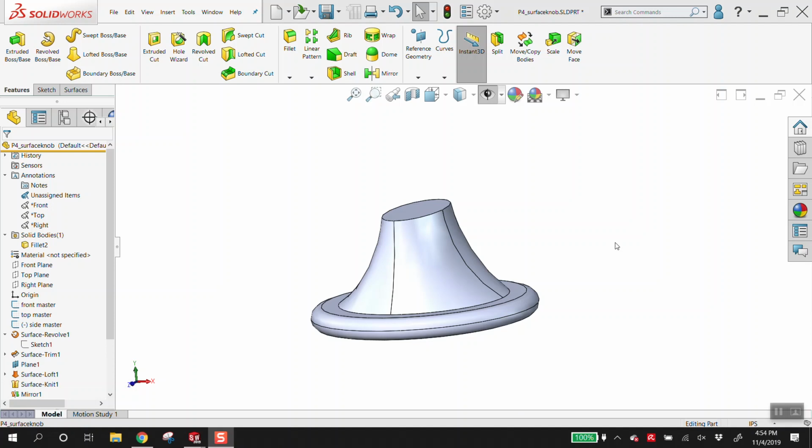So it's expected. You use surfacing to create a complicated shape and then you turn it back into a solid. Is there any time you create a surface body that can't be turned into a solid body? Sometimes, yeah, like you're trying to knit something complex, you might have a hole somewhere you can't find. Sometimes there's something weird or non-resulting that it can't knit. But for sure, if you're working on something final or going to production or making a drawing, you want it to be a solid.